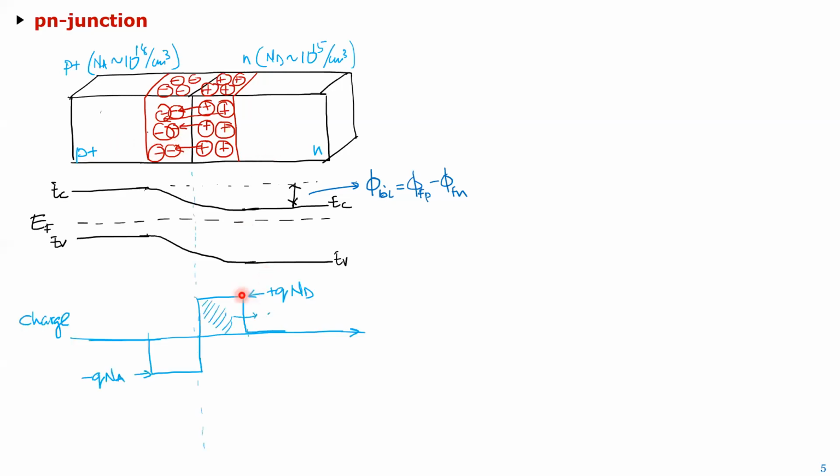Okay. And if you look at the charge, obviously you get a positive charge in this whole depletion area, which is Q times the dopant density. That's because that's your density level of your dopant atom. So if they're leaving behind the positive atom, the concentration also remains the same, which means that if I take the area under this curve, then that's the total charge in this n-type area. And if I do the same thing on the p side, that total area of this charge curve as a function of distance gives me the total charge enclosed in this particular depletion area.